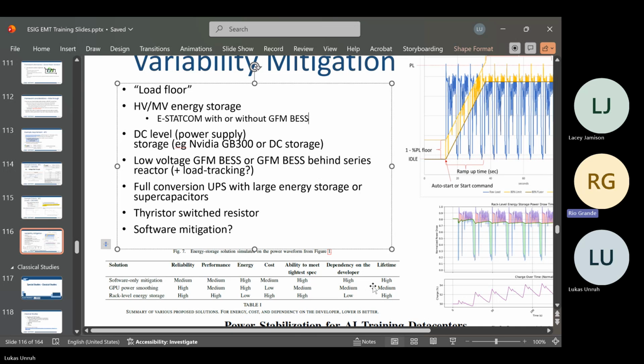Because it's measurement based, there are time delays associated with the measurement, so it's not able to offset something at like 200 hertz. That would be too fast of a fluctuation for it to be able to mitigate, but 10 hertz is definitely going to be in the bandwidth. 10 hertz and below. And they might be able to do partial mitigation. There's a roll off in terms of how effective they're going to be as you increase your frequency. And of course, the downsides are that they're expensive and they would take a long time to get.